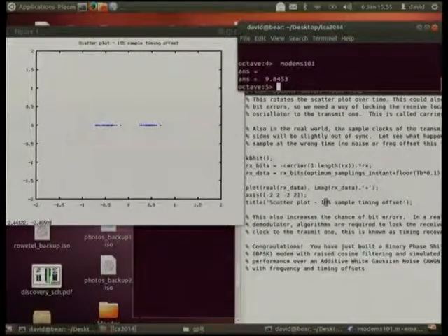So the demodulators tend to be a fair bit more complex than the modulators, as you've got to estimate parameters like frequency offsets, timing offsets, and try and get them right. Those estimation algorithms aren't perfect, so you never get exactly those perfect 2 points I showed you. You get little balls usually, and of course additive noise makes it all worse. But a good modem will maintain all that synchronisation right down to low signal to noise ratios and still give you good performance.